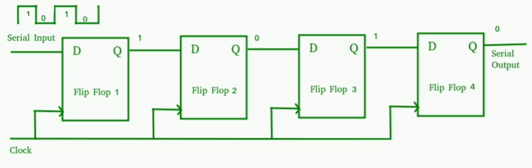The maximum number of inputs which can be applied to a logic gate is known as fan in. On the other hand, fan out of logic is the number of gates that can be driven by it. Fan out equals IOH by IIH or IOL by IIL, whichever is minimum.